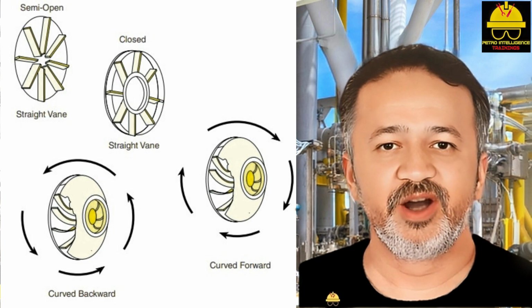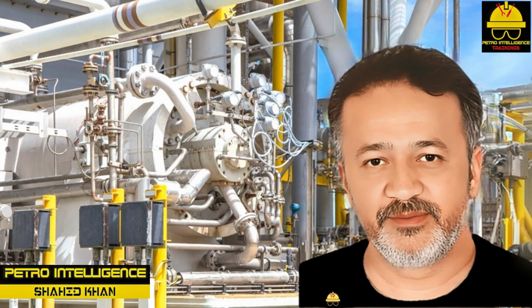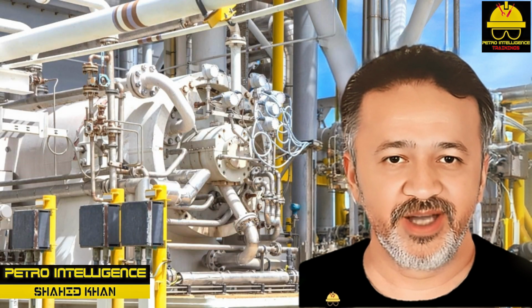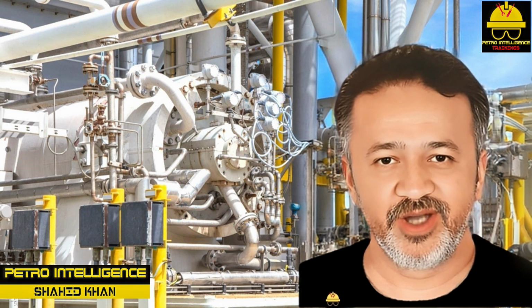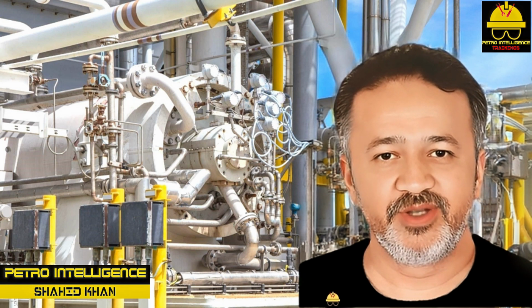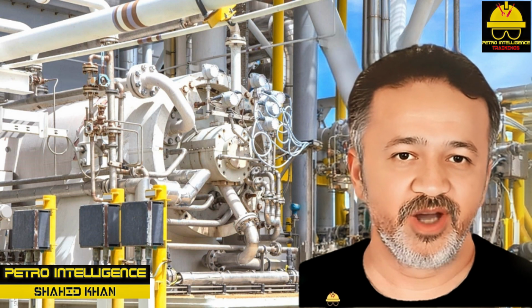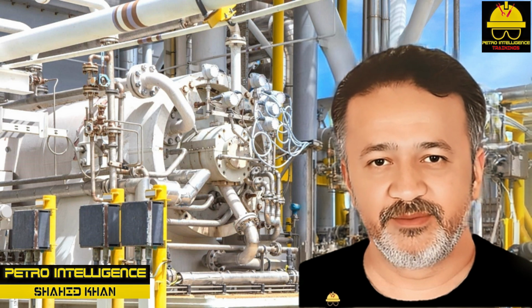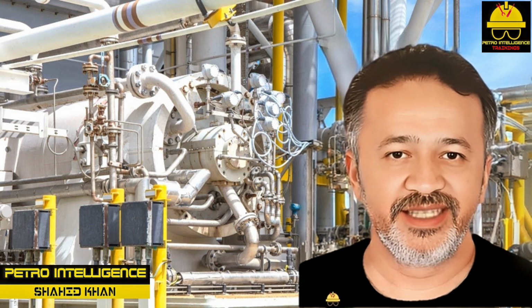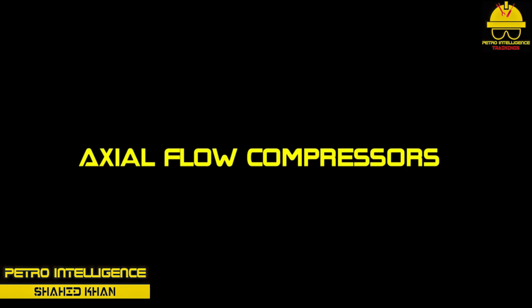Centrifugal compressors are considered to be the workhorses of the chemical processing industry. They are chosen more often than other types for new installations because they have a very low initial installation cost, low operation and maintenance cost, simple new piping installations, interchangeable drivers, large volume capacity per unit of plot area, and long service life. In addition, they can deliver much higher flow rates than positive displacement compressors.